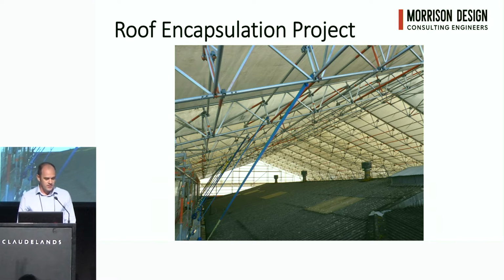The ends of these trusses, to stop it from taking to flight, we would usually attach to the building, either using mechanical anchors or chemical anchors, or sometimes we'll add concrete or water counterweights at both ends. You can see here in the photo, we've got a truck strop in blue there, and that's cutting down the effective length in the uplift condition for the scaffold. So it's fine for the downward, where it's got plenty of strength, but for the uplift, we've got those strops cutting down the span.